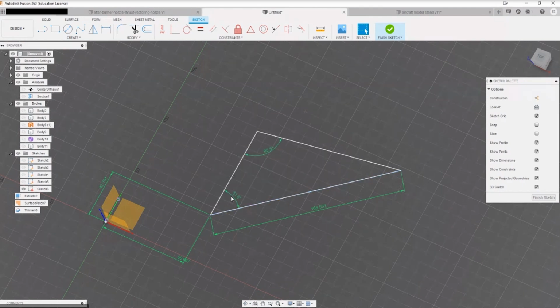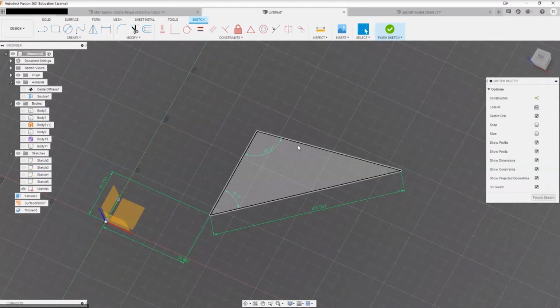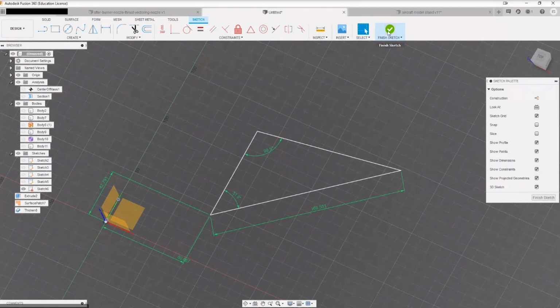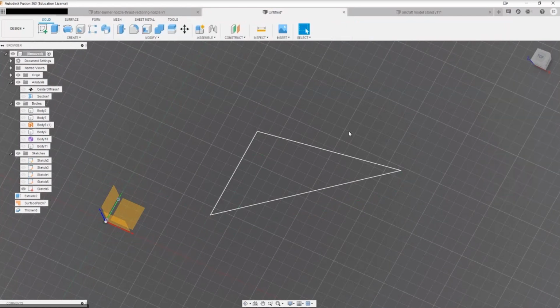And you should absolutely get into that frame of thinking that I'm not going to just move a component and sort of eyeball it so it's close to another component in an assembly. No, actually use a tool, use the move tool, and specify the exact distance. Believe me, it's that much more professional, and it's going to really help you in the long run in that respect. Okay, so that's to constrain the different points.